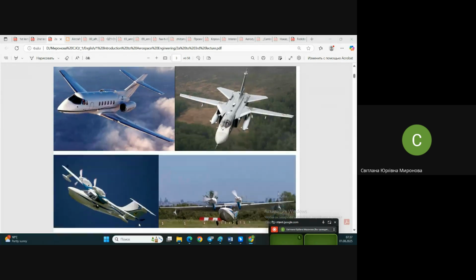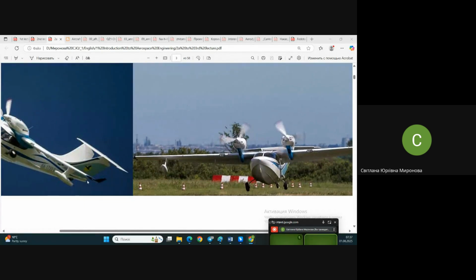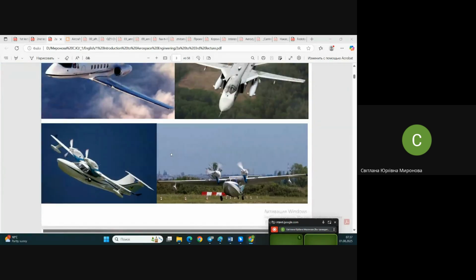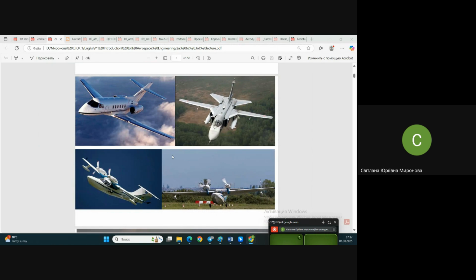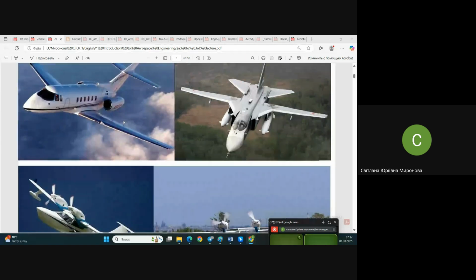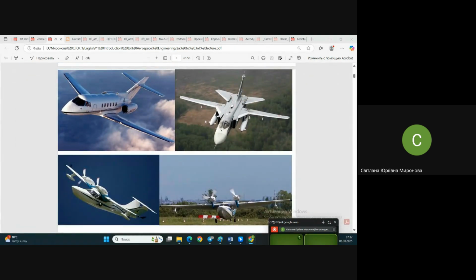No, in this photo it's somehow visible that this is subsonic, but for you it should certainly be visible that it's subsonic. By another side, what about this? No, rather sharp nose. Circular profile, yes, maybe circular profile is here. That one certainly is supersonic by its shapes. But what about the wing? Wing here is practically straight. No, maybe it's tapered, but not much visible in this photo.